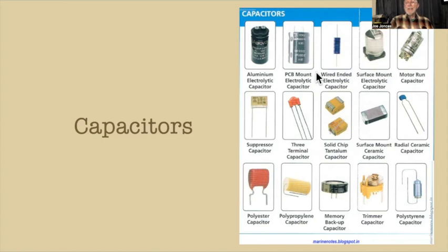See all these capacitors here? These are all different kinds of capacitors with different kinds of application. This is an electrolytic capacitor. It has foil in it that's rolled up, and in between the foil is paper, and the paper is soaked with a chemical. And when these are formed, they get polarized in one direction. When they get polarized, their capacitance increases. So these are the kind of things that you find in power supplies.